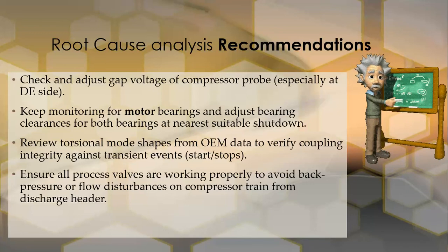At the end, we recommended that we should take a sample from the liquid that comes from the drain lines and also the discharge lines to make a composition analysis, to be sure of the content and the composition of the liquid that comes out of the compressor and the discharge lines, to avoid a problem of whole system failure.